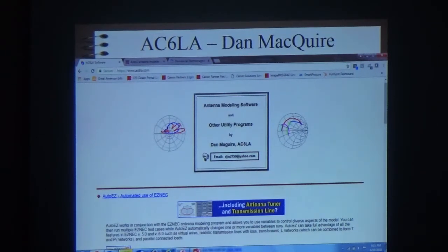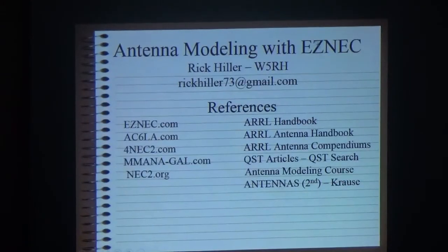No, it was efficiency. Sorry, a friend of mine had a package. I can't remember what he was using, but they had this thing called a characteristic antenna efficiency. And when he was looking for a new package, he was talking about EZNEC with me, and I said, "Oh, EZNEC's great." He says, "Well, where's the efficiency tag?" There isn't any efficiency tag in EZNEC. "Oh, well, this program has it." I said, to do efficiency, you have to put everything to lossless, run it, and then put everything to realistic and run it, and look at the difference. And that's how you get it. And even Roy says that in the manual.